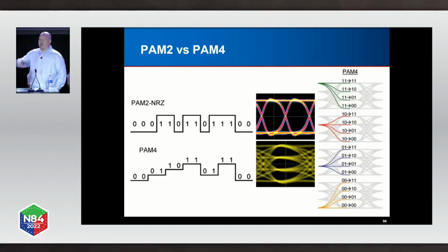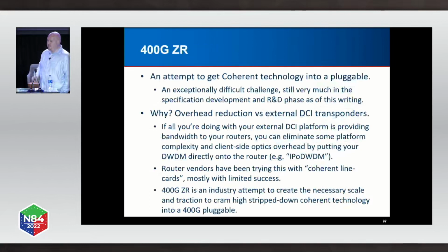And this is the eye pattern of what that looks like as the thing crosses and how you're able to detect. So what you can do is move into something called PAM4. So you add 4 states, and then as you cross, you encode 2 bits per symbol change, and so you walk away. These are the states and what that would map to. So I think I probably have a slide on that later.